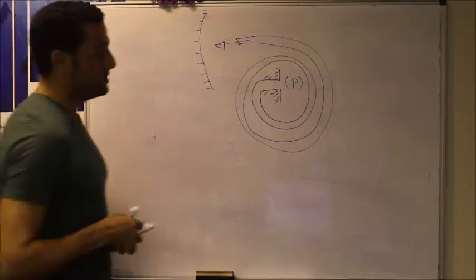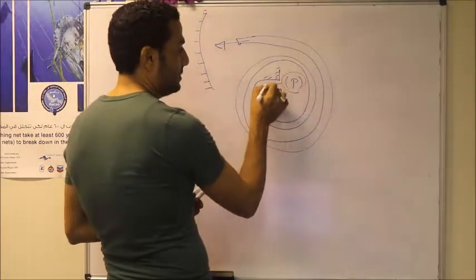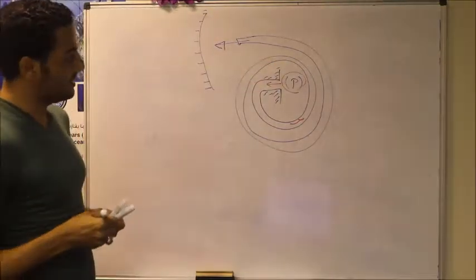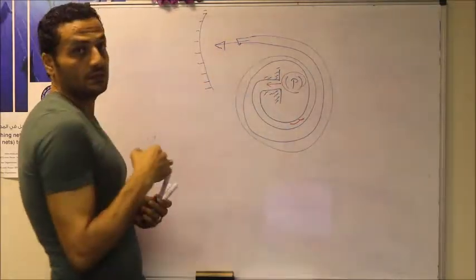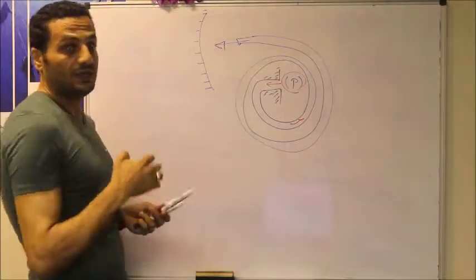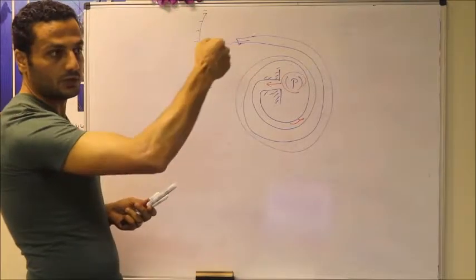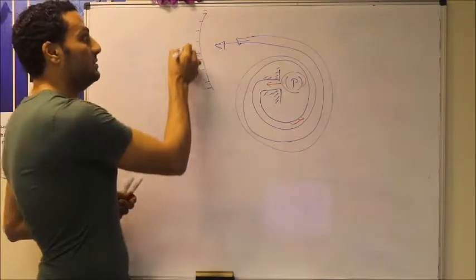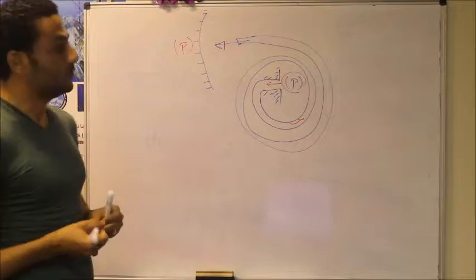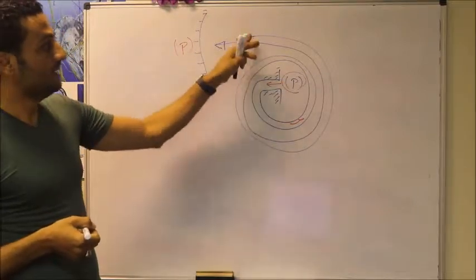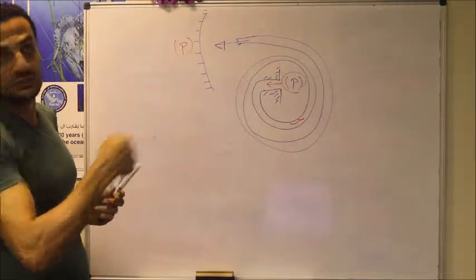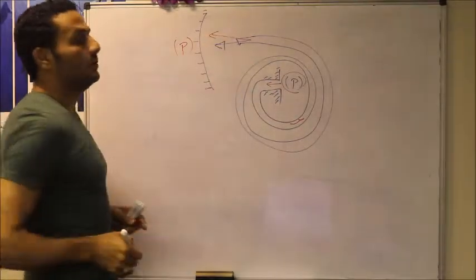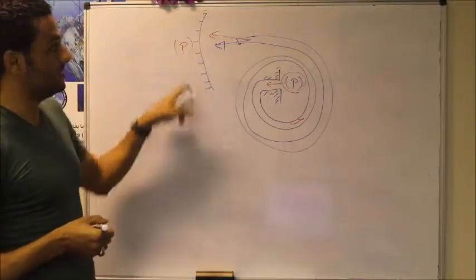The idea is that when we subject this device to a pressure P, the flow at this pressure will get into this spiral tube. So what will happen in this case? This end is open and this end is closed. So the flow will get inside, and depending on this pressure the free end will try to deflect with a certain angle. This deflection is calibrated so that we can read the pressure value on this scale. So depending on the pressure, the flow will get inside, and this free end, due to pressure, will be twisted with a certain angle. Based on this twisted angle we can read the value of the pressure, and this scale is calibrated.